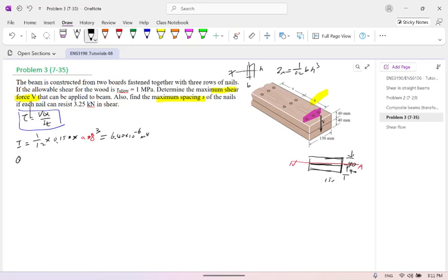And the Q max, of course, Q max will be at halfway of these things. So that's Y bar times A bar. So the half of these things, this one will be on top of this. Clear? So Y bar will be half of 0.04 meter times the area, times the height. So we can work that out.